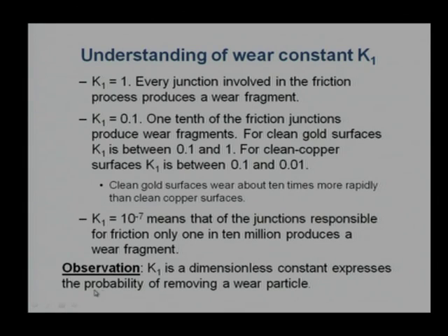So, we can use the word probability for K1. It is a probability of removing a wear particle. Again, in this overall expression, we assume only spherical asperities. We do not assume any other asperity, but there is a possibility of other forms of asperities, and then K1 will be slightly higher than for spherical, and the wear rate will be slightly higher.